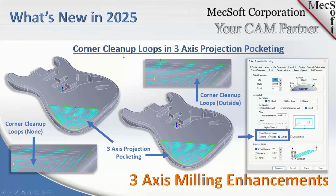This is one of our advanced 3-axis methods, 3-axis projection pocketing, where the toolpath is calculated and then projected in the z-axis down onto the part. In previous versions, if you look on the left here, the result would be these sharp corners. It would calculate the offset, and then project it down onto the part surface, and then you'd have these really sharp corners that could cause some jerking motion in the CNC machine. As the tool goes to those corners, it has to stop, change direction, etc.